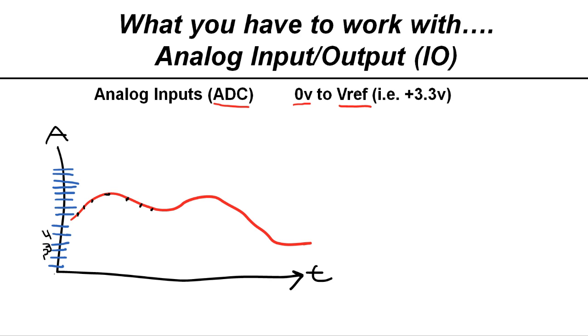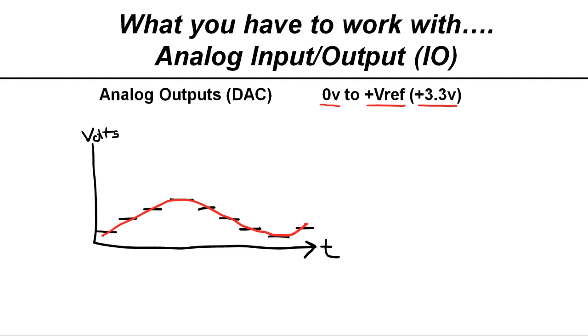But what I want you to take away here is that if you have some sort of analog signal, say from a sensor, we would wire it up to an analog to digital converter, and almost all microcontrollers have these built in. Now, here's a little anecdote: more often than not, microcontrollers will have an analog to digital converter built in, but not quite as many have a DAC. It's more common to see it the other way around.